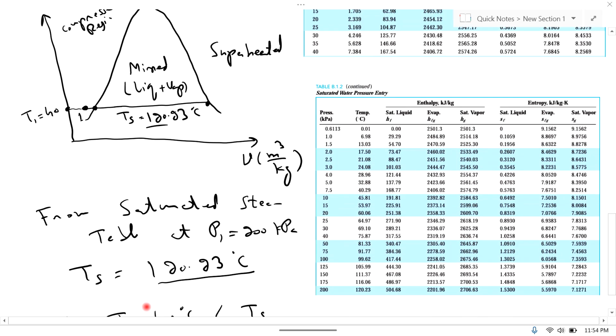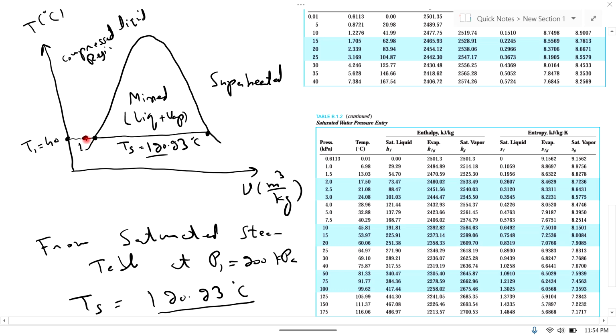And finally the steam is dry saturated. This is the initial point, then in this region, this is a constant pressure line. So finally it is dry saturated, and this is the saturated liquid line, and this is the saturated vapor line. At this point the vapor is completely dry.